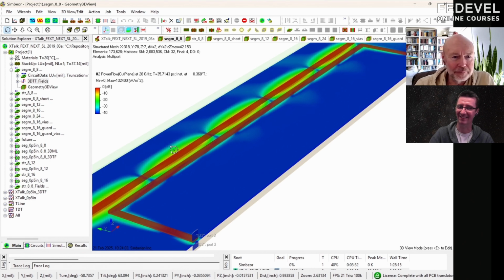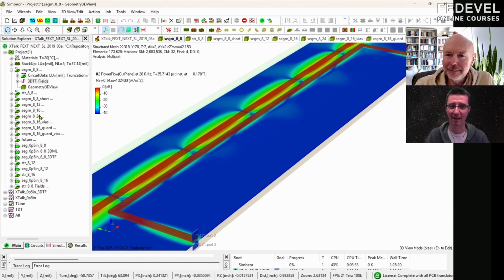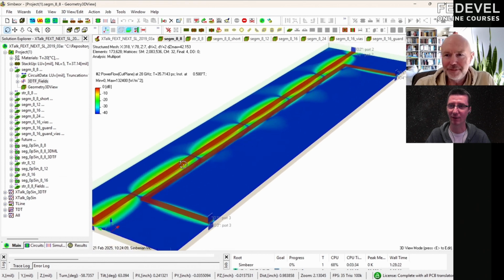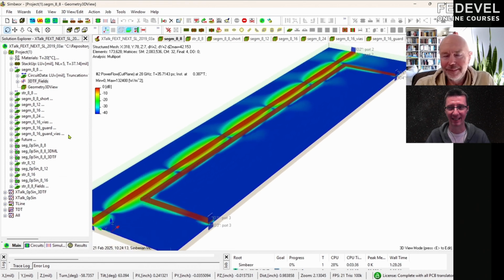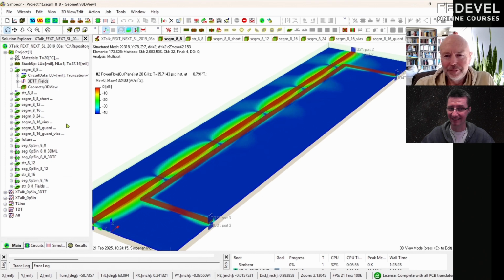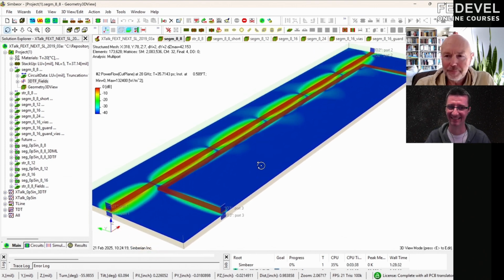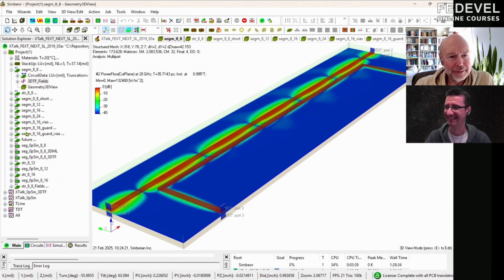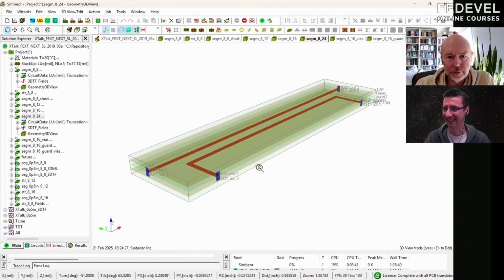Yeah, okay. For instance, let's have a look. Well, I guess there are a few ideas people may come up with on how to prevent this. One of them is to place the tracks further apart, and the other one, which we very often see, is placing ground traces between these two tracks. Okay, I pre-computed those cases, and if you put them further apart, like this.